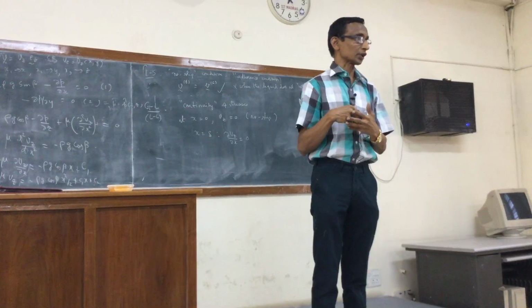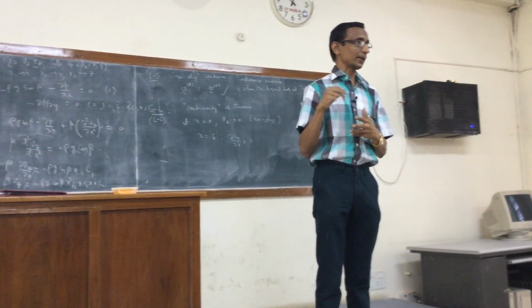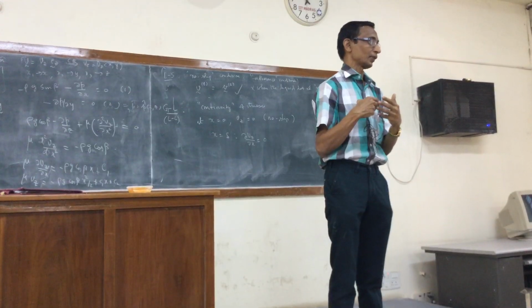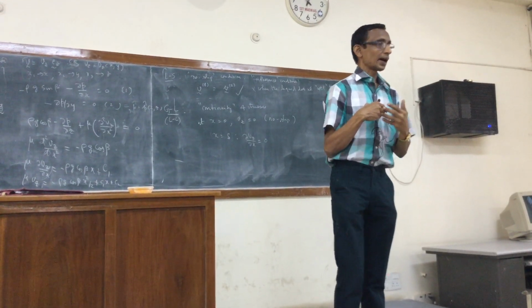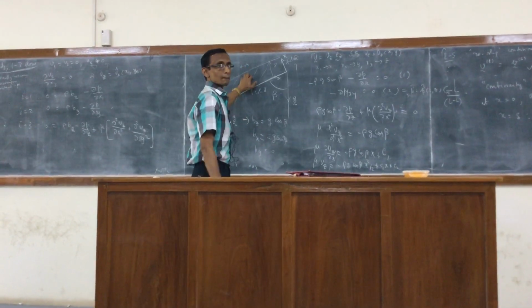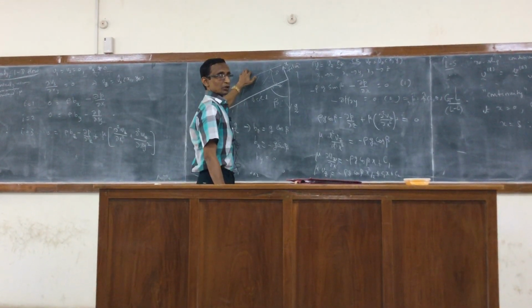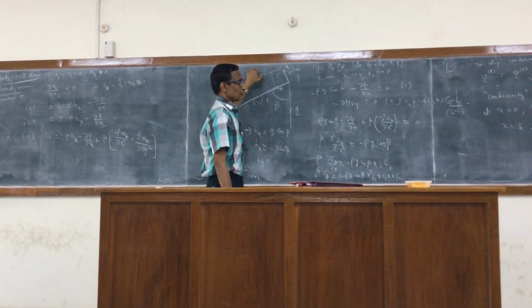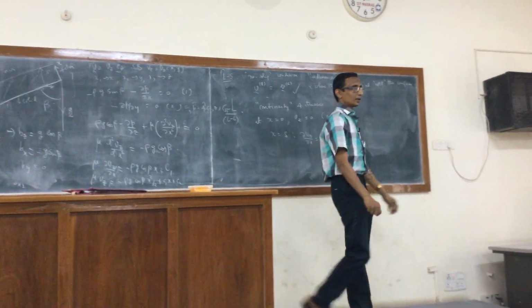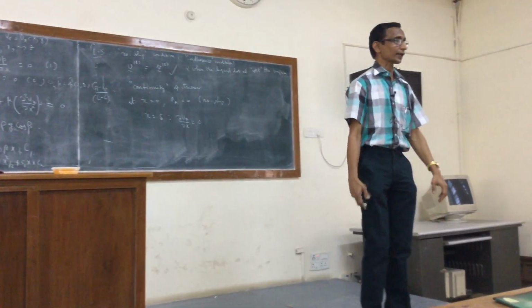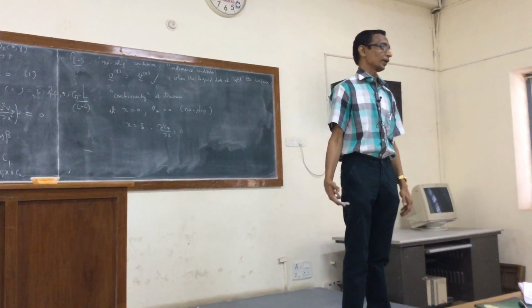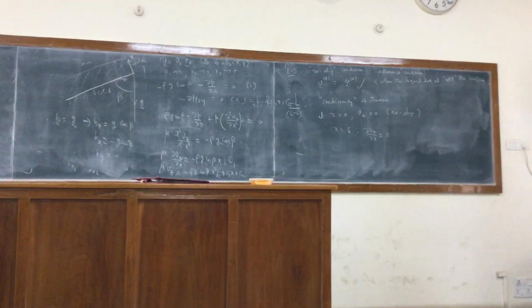We'll come to that shortly. But what it effectively says is that not only the shear stress but the normal stress also must be the same, right? At the interface, which would mean effectively that the derivative of the velocity with respect to x has to vanish, right? That is the condition that we get on the velocity component.